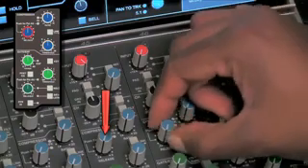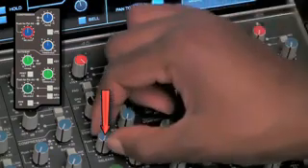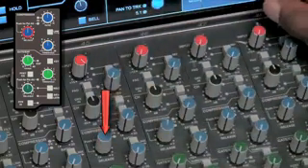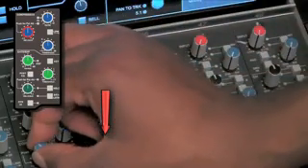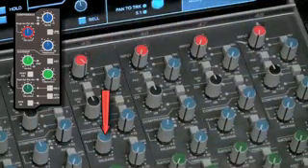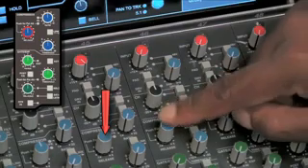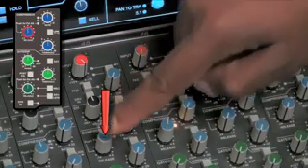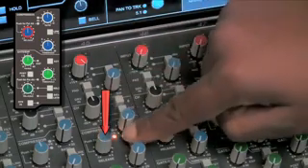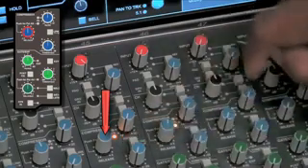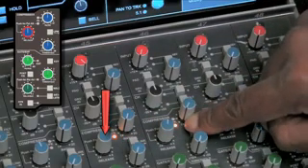The release pot controls the time it takes the compressor to return back to normal gain settings once the signal has fallen below the compressor's threshold. This control also incorporates a push-push switch used to select a fast attack. This gives you a variation to the standard attack time.